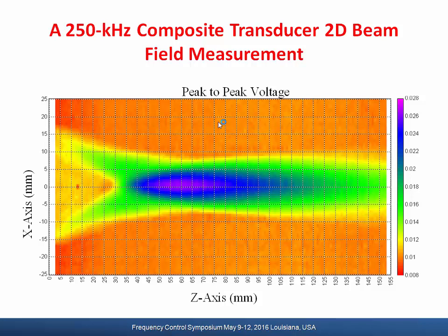So we have the near field, focal zone, and far field. The focal zone is from 40 mm to about 100 mm. This is our usable operation range. It's wide, and beyond 100 mm, that is the far field, where energy dies out and spreads out quickly.